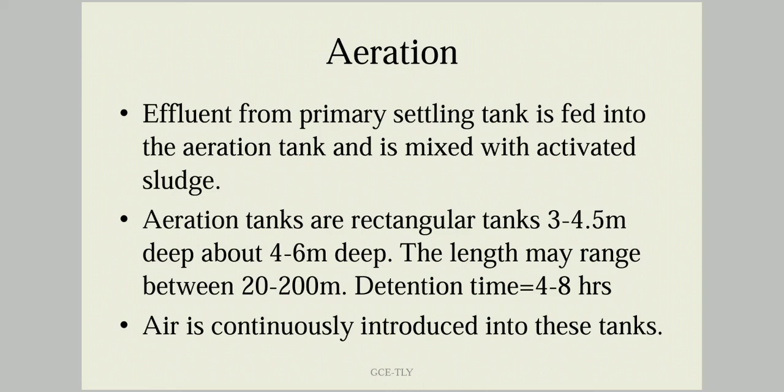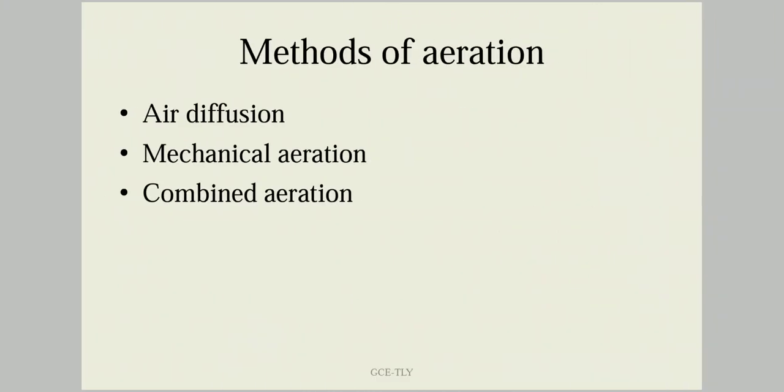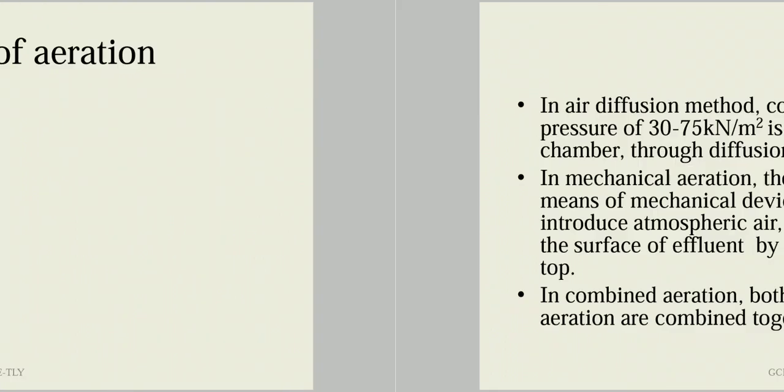Air is continuously introduced into these tanks in order to facilitate the aerobic reaction. So we use an aerobic process, and the aeration tank is continuously stirred to mix the effluent properly with the aeration. Aeration is provided regularly. The aeration is done by three methods: one is the air diffusion mechanism, another is mechanical aeration, and another is combined aeration.